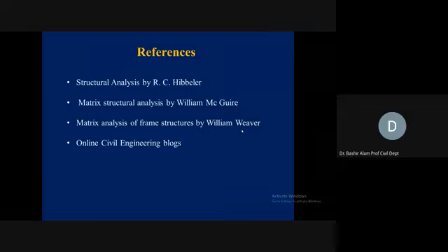and we write the capital M equations for each member. Then turn by turn, we apply the unit redundant actions corresponding to their locations and generate the M1, M2, and so on values for each member. After that, we complete the bending moment equations table, which has the information about the segments, their lengths, the moment of inertia, their capital M values, and M1, M2, and M3 values.